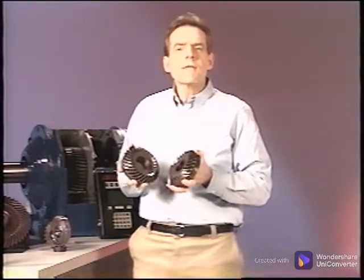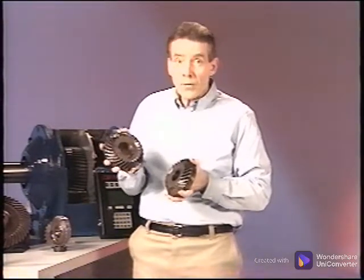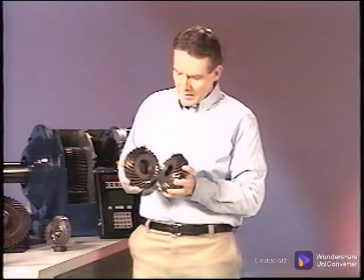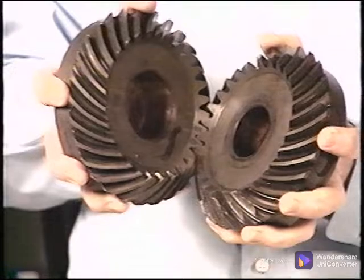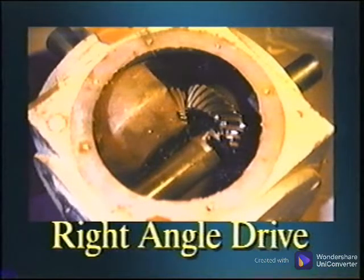Bevel gears are similar to helical gears, except that they are cut on a cone shape and work with intersecting axes. The teeth can be either straight cut or spiral cut like these. A common application is a right-angle drive. They are similar to spur gears in their operation, but are much more sensitive to assembly dimensions. They should not be used for high-speed drives or where extremely high accuracy is required.